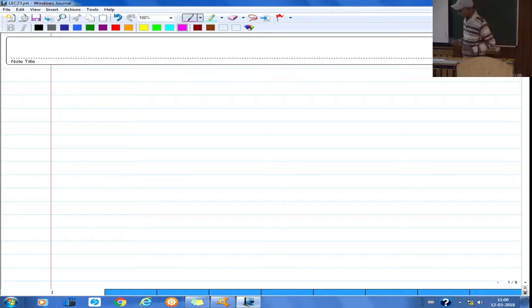No, we have not. For which case are you saying? For the plane stress, plane strain problem? This term is that. These both are external. No, I was saying that the boundary traction on the element is actually internal. Of course, when you are solving the entire problem, this could also be on the boundary of the entire domain. There can be externally prescribed traction, but otherwise, when you are talking of the element, it is internal only.